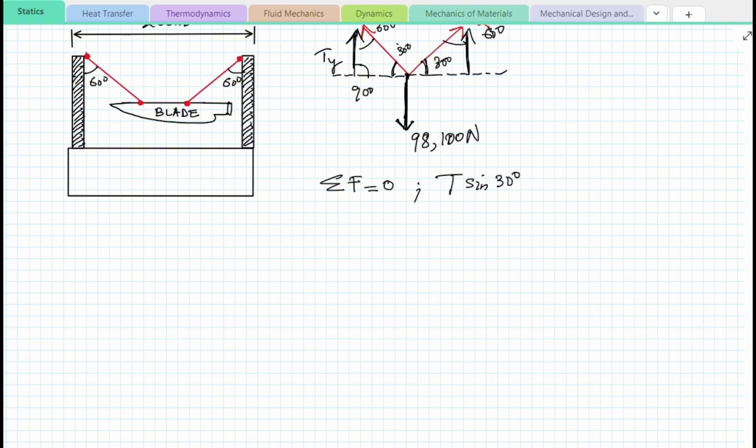So, during the FE exam, your time is very limited, so you don't want to spend time writing out every single thing. But, just for illustration purposes here, I'm going to write down both Tys, if you will. However, for an exam like the FE exam where time is of essence, you want to make sure that as you're solving the problem, you skip things that, quote unquote, make sense. So we'll have T sine 30 degrees plus T sine 30 degrees. So that's this Ty here.